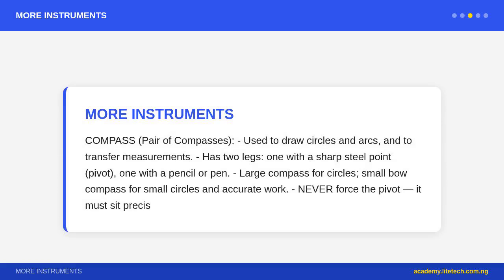Ruler/scale rule. For measuring lengths. Scale rules show multiple scales: 1:1, 1:2, 1:5, 1:10, 1:50, 1:100, 1:200, 1:500. 1:50 scale means 1 mm on paper equals 50 mm in reality. Used for building drawings. Read dimensions by placing scale flat on paper, do not angle it.